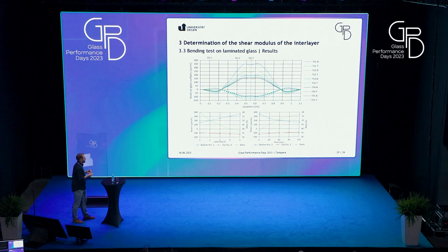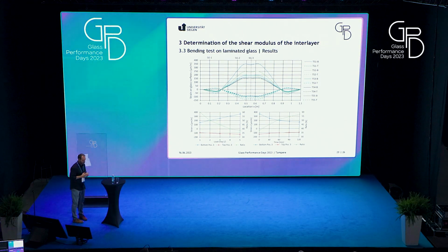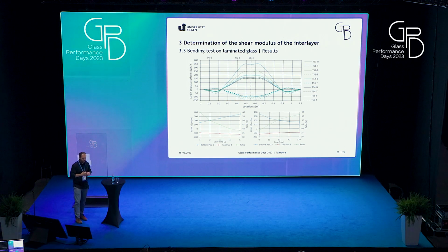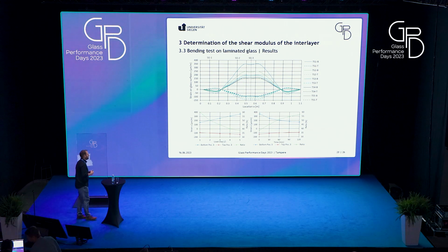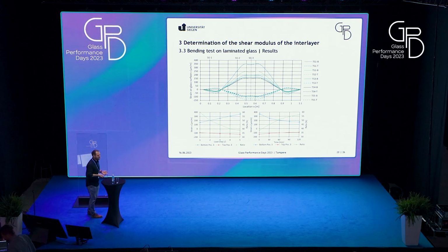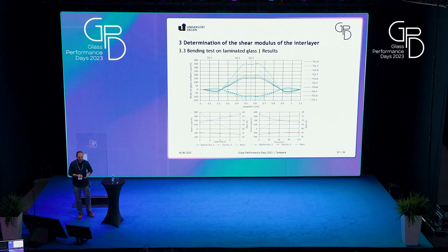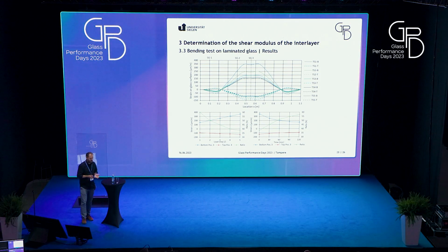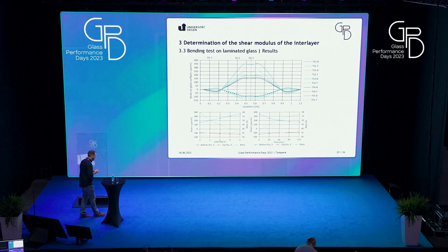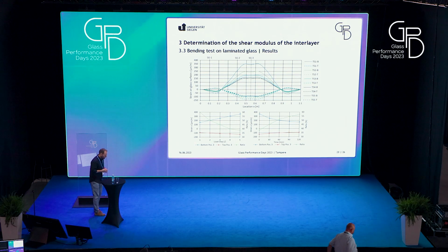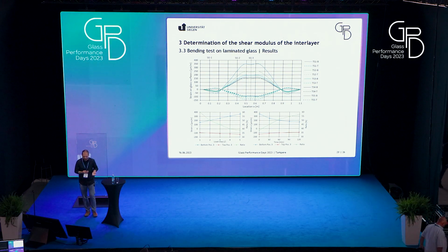And you can see that the connection between the glass panes decreases with the load steps, and they increase with the time. So this is something not new, it's not special, but it shows that it is similar to the tensile test. So we can use values from the tensile test and as well from the DMTA to model the time and the temperature dependence.